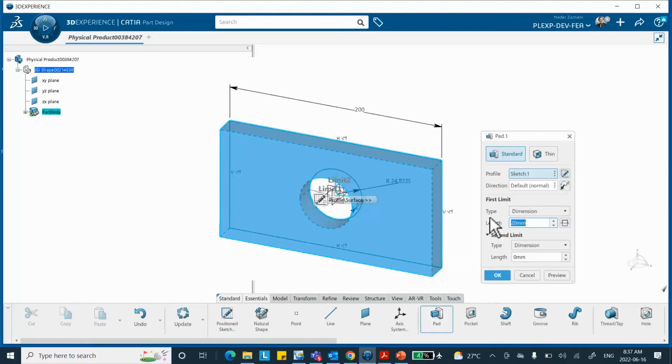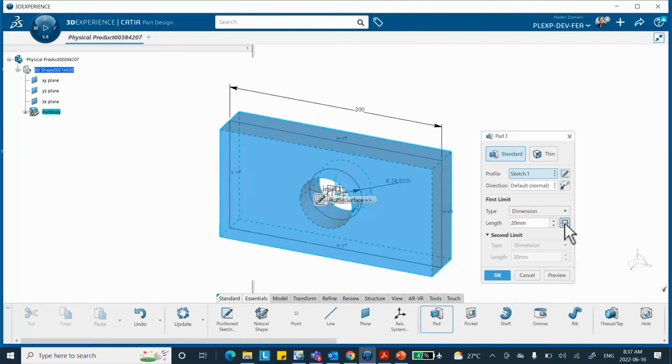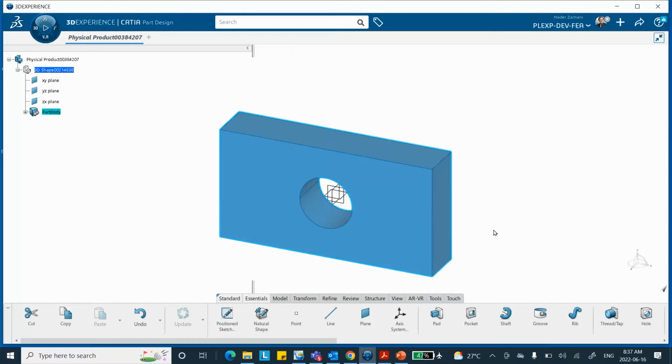Padded. Now, this dialog box is essentially the same information, but there is no mirror extent. You can see that. But on down here, see that? This icon? It says basically mirror it. I'm going to select this. It does it on both sides. Instead of mirror extent, there, one side, two sides. Numbers are the same, exactly the same stuff. There we are.